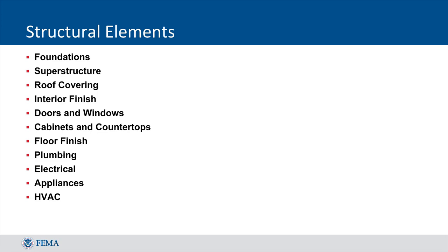We'll take a look at photos of some of the different ranges of damage for each element so that you have a baseline to work from when evaluating different structures. Although many of the photos show damage from flood events, damage from any source should be taken into account when evaluating a structure, not just damage from flooding. In most cases, you will look for the same indicators for other sources of damage as you would for flooding, so these photos provide a good example of what to look for in most cases.